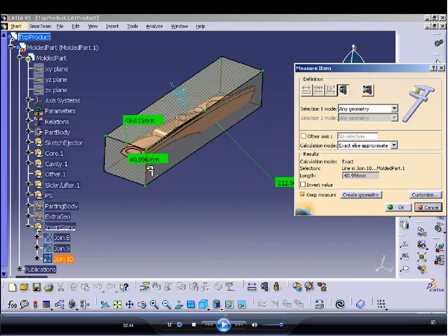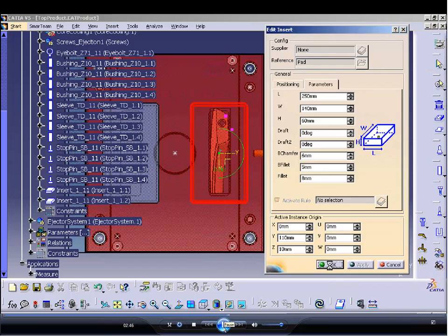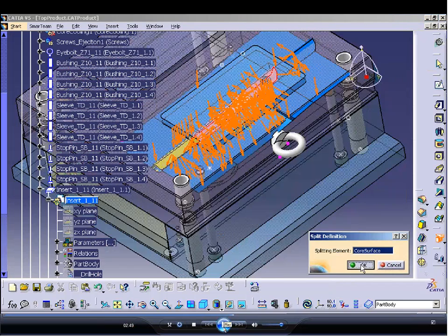If it can't find a size that fits our criteria, we can have it automatically build one and then add it to the catalog. But typically, most people like to take something that's standard because it's cheaper. We're in the process of including information based off of the type of mold that you're going to be building, whether it's plastic injection molding or whatever you're going to be doing, and whatever the tonnage is and everything else. So we can actually go through all that process of defining the tooling so we pick the right one. So in this case here, we picked this first template. It also will generate all the drawings and manufacturing information along with it at the same time.